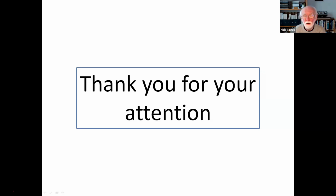So I entirely understand what you're saying, and as I say, it's a personal decision. But I know Fusion, Solid Edge, FreeCAD, they all do very much the same sort of things, so I'm quite sure that you can produce decent results with any of them. I think with Fusion, one important thing is because it's cloud based, to make sure you save your drawings onto your own machine. So export them as an F3D file, so at least you've got your own copy if anything happens to it in the future.